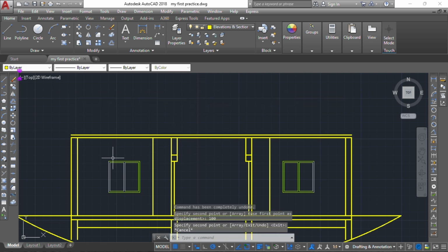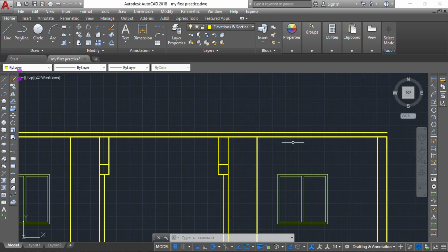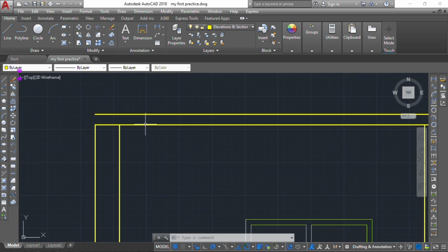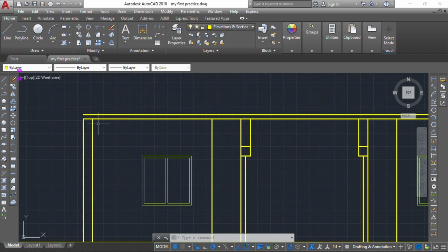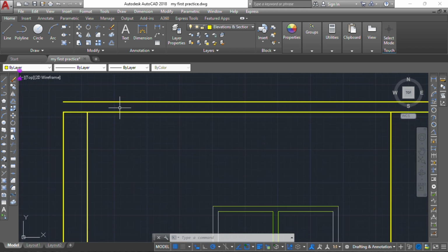Which is our wall plate, the wood that is going to be laid across our wall, to which the roof is going to be attached. And meanwhile, this wall plate is not nailed down to the blockwork, right? It's not possible. Now we are having another thin iron, either a round iron or an iron sheet, tying the wall with the wood of the roof, right? Which is known as the tie beam, right? Okay, now let's just go ahead and create our tie beam.